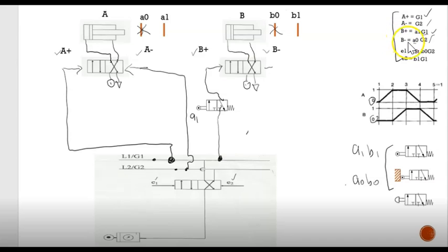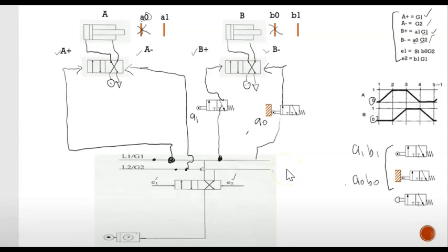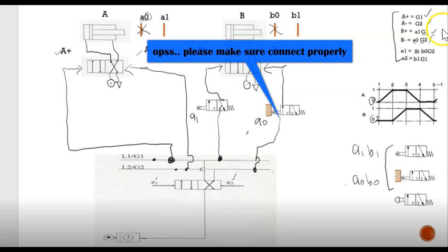Next we're going to do B minus, A0 G2. We know that A0 is this switch, so we bring it here and name it A0. Since this is a contact limit switch, we're going to use this side, link it to this arrow, and it's going to go to G2. G2 is here, and make sure you do the loop here. Okay, next, so we're done.